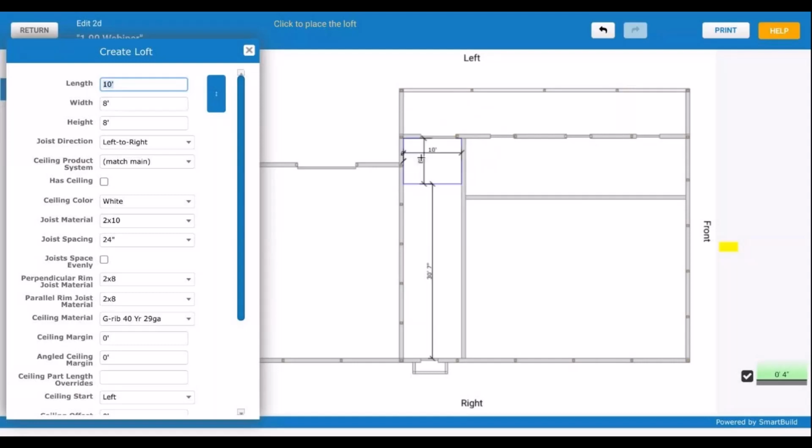And in this case, we already have 10 foot by 8, which is kind of the default. One trick that you can do here, if you put in a plus, and I'm going to put in 3.5 inches, it'll just add that to whatever dimension you already have in there. So that will put us into this other wall, and I guess I did do 2x6 walls, so maybe it'd make more sense to do 5.5, but whatever you need to do there.